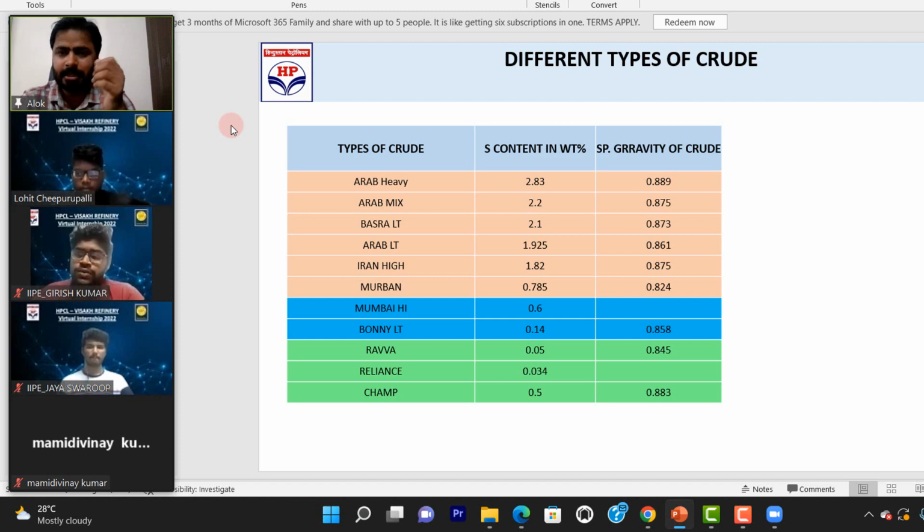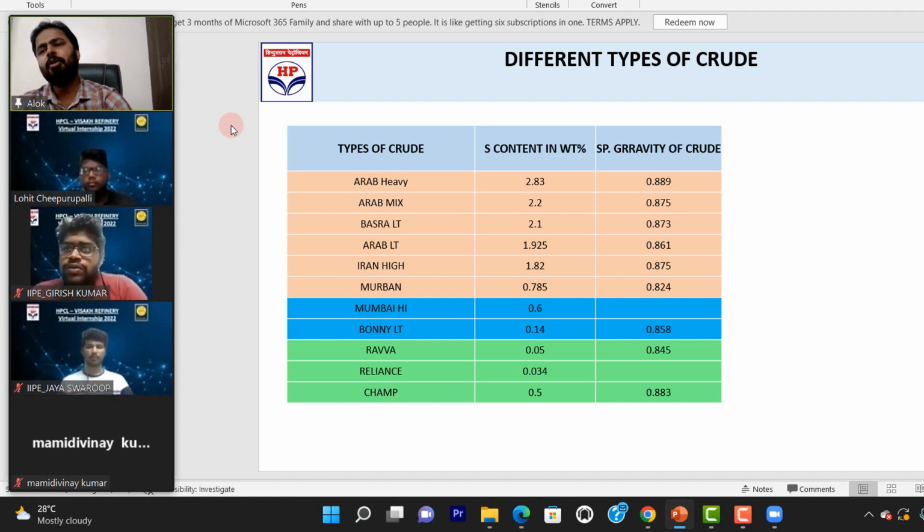But you guys read, I'm coming back to the topic. So, the spent catalyst slide valve: basically we maintain a level, and whatever excess catalyst is there, the slide valve will open and the spent catalyst goes to the regenerator. On the spent catalyst, carbon will be there. So this cycle keeps going on. This is how basically we are maintaining the reactor-regenerator profile, correct? Basically so many parameters are there in detail. When I go into the operation, how we are operating the reactor-regenerator, I'll explain.